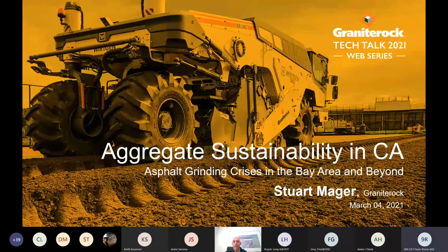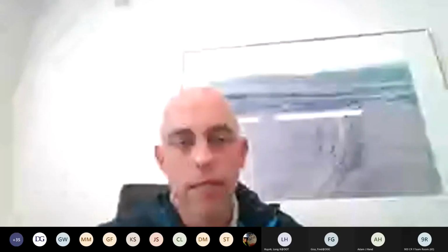Sorry. From your stockpile photo, what is the difference between clean grindings and RAP? Let me go back here. So clean grindings is what's coming off from the millings from any grinding operation. Clean grindings would be strictly grindings, no underneath base material. RAP is what we do after, if you look over here, if you can see where my cursor is, that material's taken over here and put through a crusher.